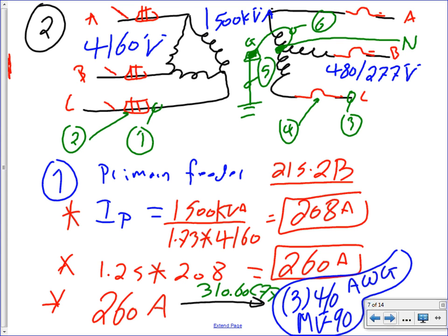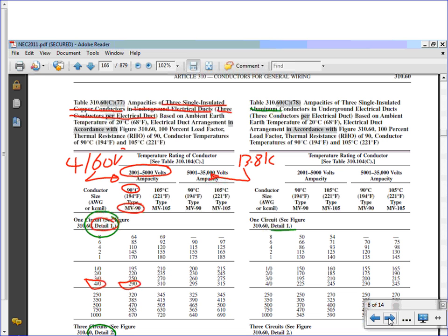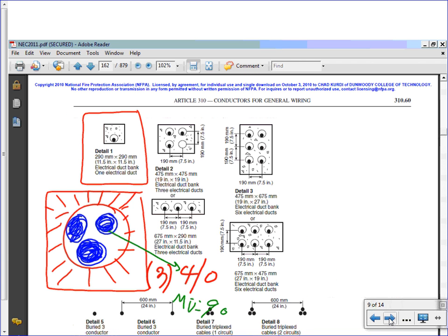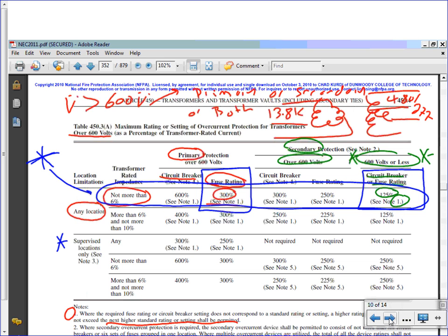If you are faced with a situation like this, what do you do? You go to this table, you default. That's like 310.15(B)(16). Exactly, you default. Which column? 90-degree column. Okay, so let's go back here, guys. One more time, your default is a 90-degree column. But why did we go to this set of columns, not this set? Because of our voltage. The next example you're going to see, we're going to be using the second set. Okay, here's my default, 2, every 4-aught.